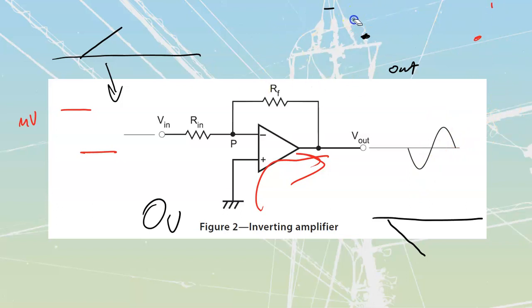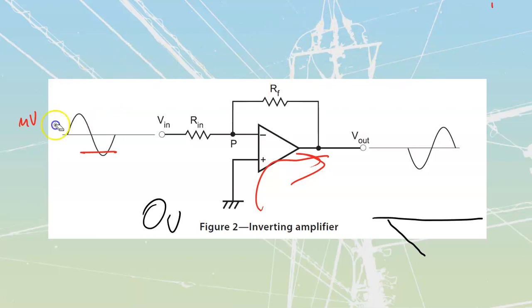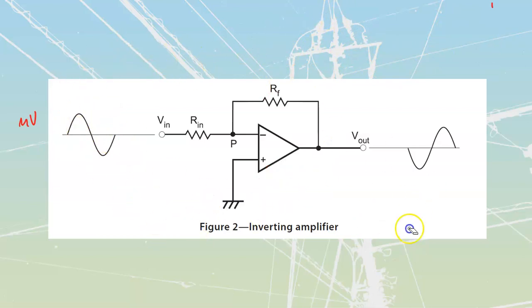That formula that describes it is going to be my amplification closed loop, or my ACL. We talked about AOL, which is the amplification open loop before. This is now going to be ACL. A subscript C subscript L, amplification closed loop, is going to be this value of my RF over top of my Rin. The F stands for feedback on this one, my feedback value of resistor. The ratio of my feedback over top of my input resistor is going to determine how far we are going to drive that amplification closed loop in the opposite direction.